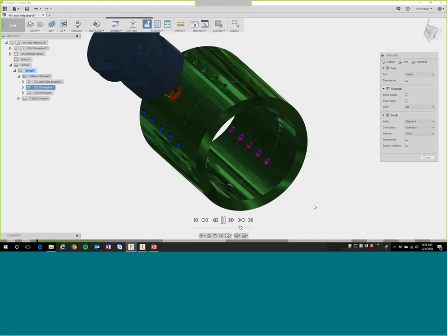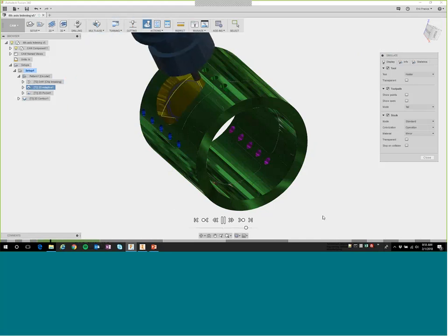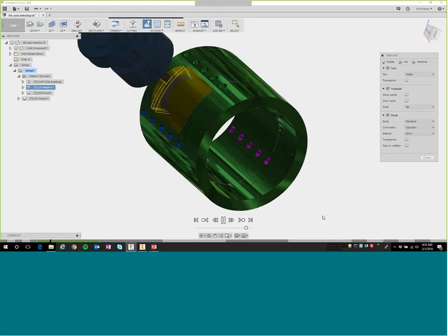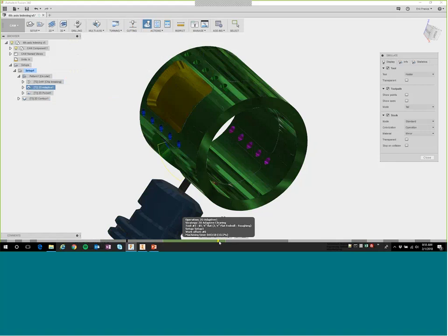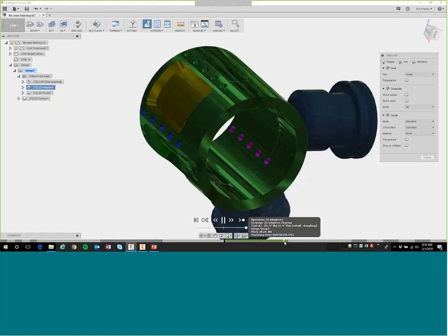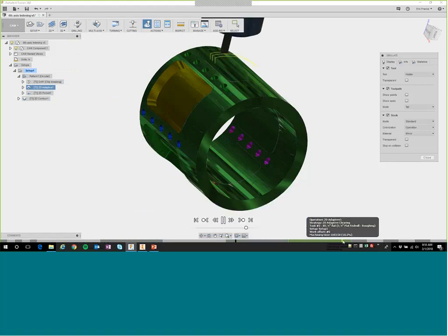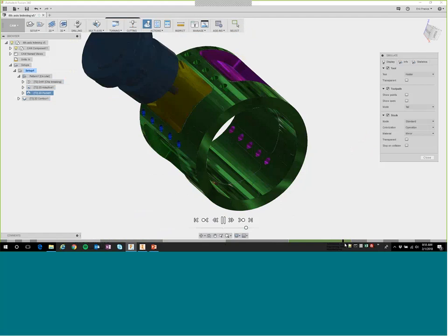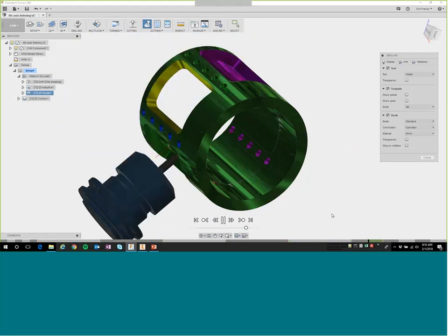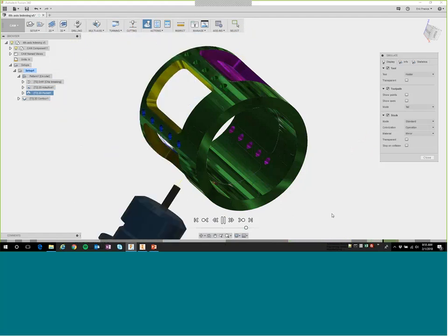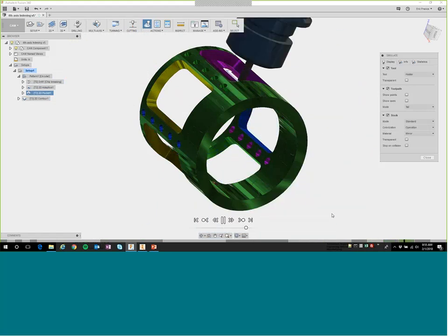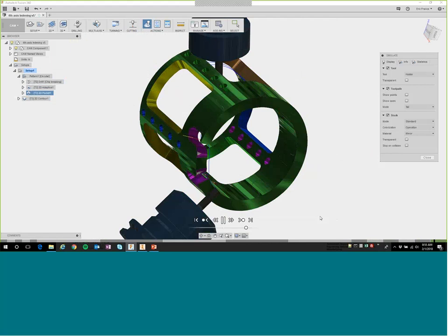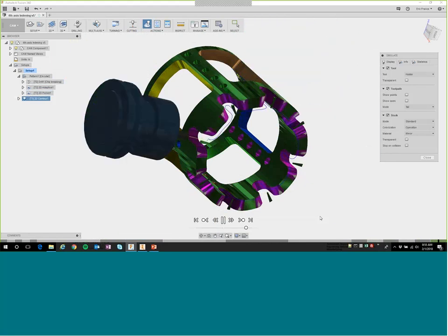And now it's going in, and we're going to speed this up a bit more to move through the rest of this geometry. Right? But it's going in and doing those milling operations or the clearing operations, which really don't show us a whole lot. Right? But now we can see it there. It's clearing out all that material, actually breaking through. The nice thing about doing that roughing operation, leaving some material and then coming back in, and there it's going in and doing the contour.